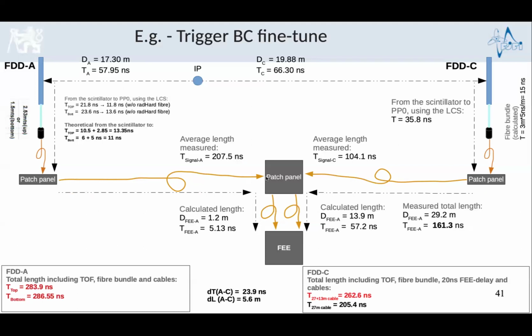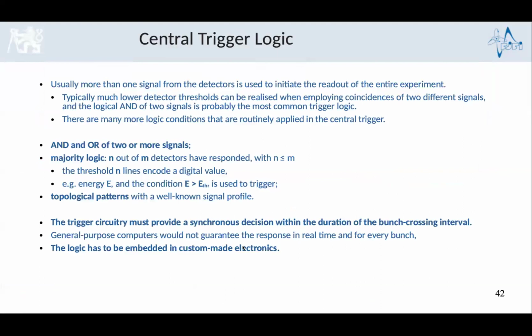Yes, one has to synchronize these cables, selecting the proper cables to adjust the latency of the signals to the front end. So this has to be done channel by channel. This is a very important task.